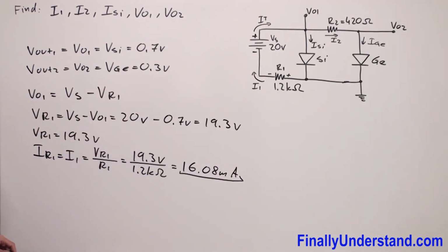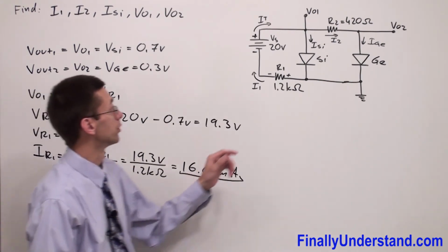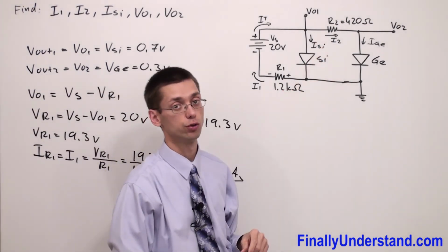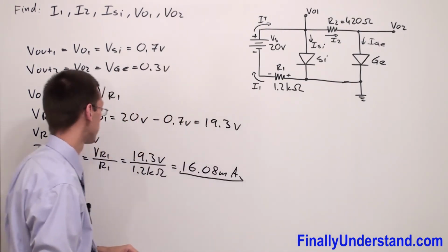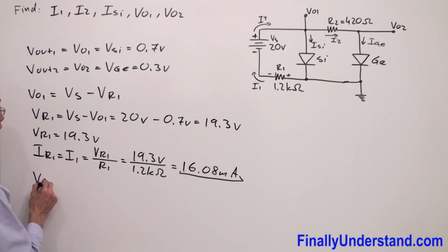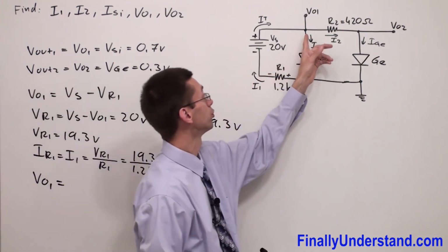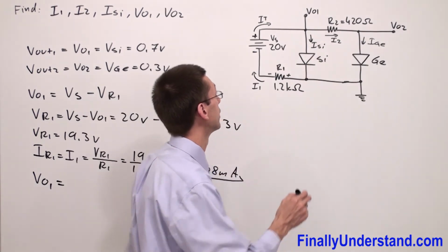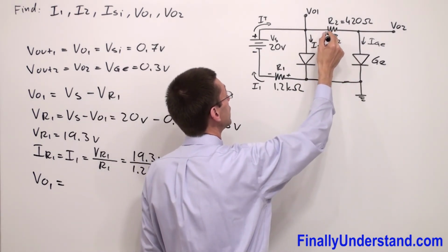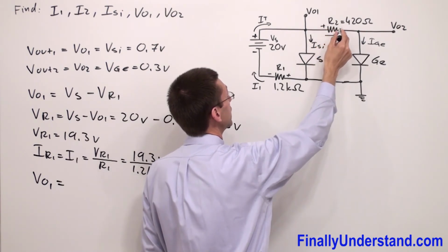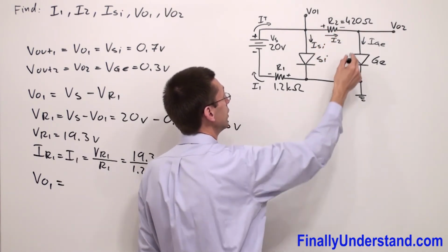Okay, so if I want to find the current which goes through the resistor R2, I'm going to simply write that V out 1 is equal to, this time I'm going to write the KVL for this branch. So anytime current is entering the component, I'm supposed to write positive sign. Anytime it's leaving, I'm supposed to write negative.